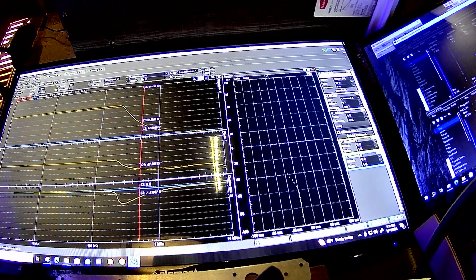If you get out a calculator, you can set this voltage to whatever. If I wanted 10 volts peak to peak output, that's 5 volts divided by 3, so about 1.66 volts is where you really want to be.